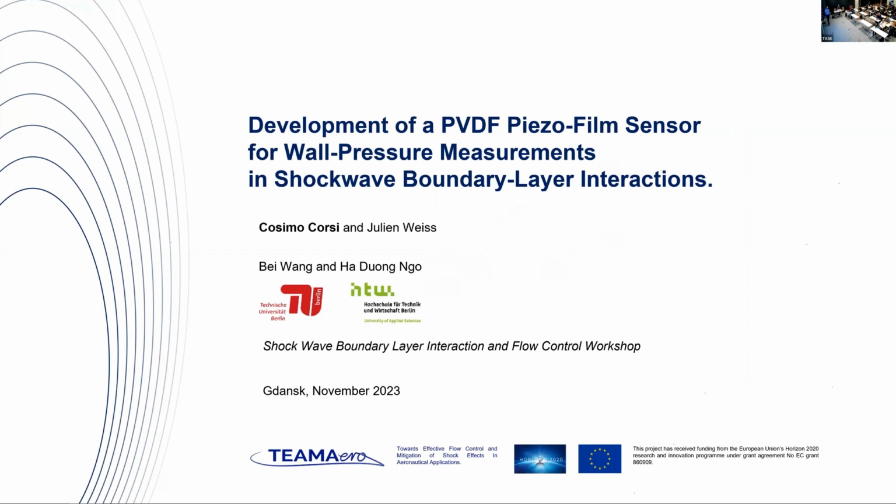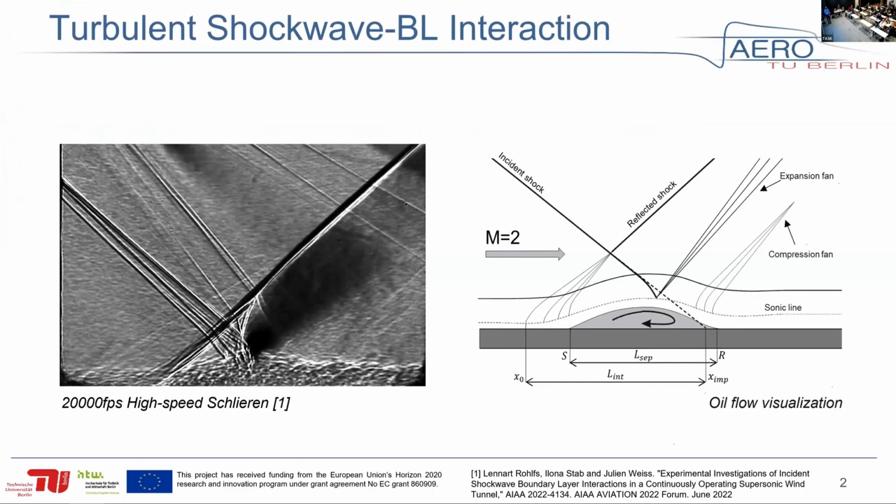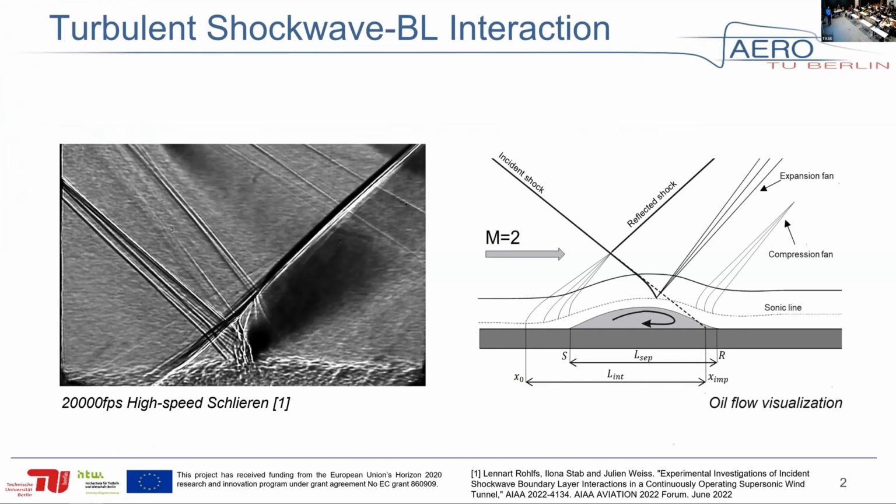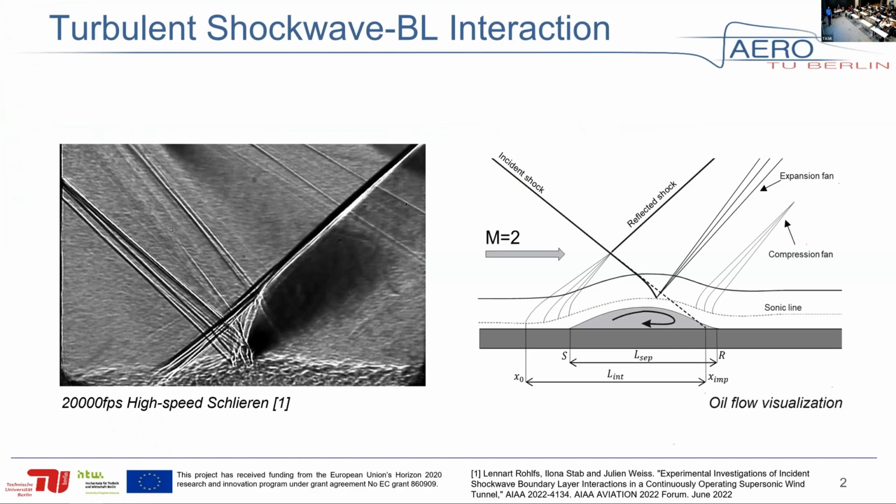The work that I will present today has been carried out also in collaboration with the University of Applied Science in Berlin. And we developed a novel technique for the measurement of wall pressure fluctuations in shockwave boundary layer interactions. And this new technique is based on piezoelectric thin foils. First of all, I will introduce the flow case that we analyzed in our supersonic wind tunnel.